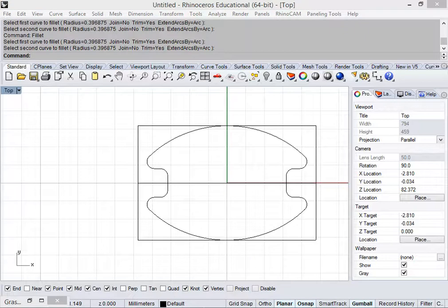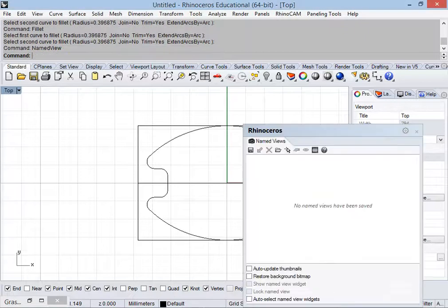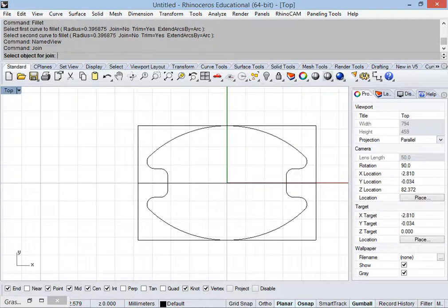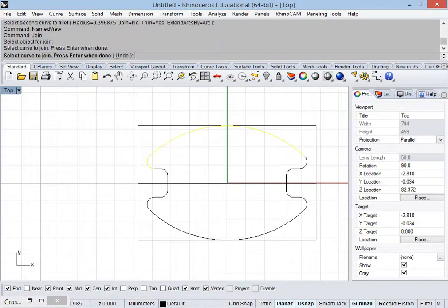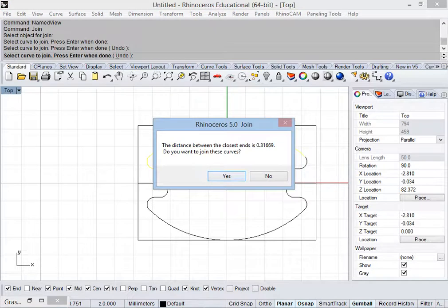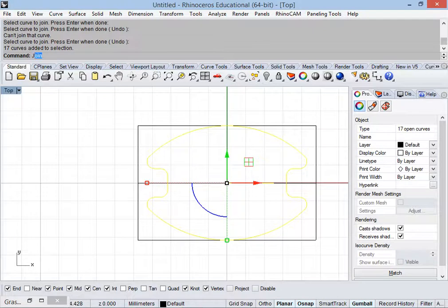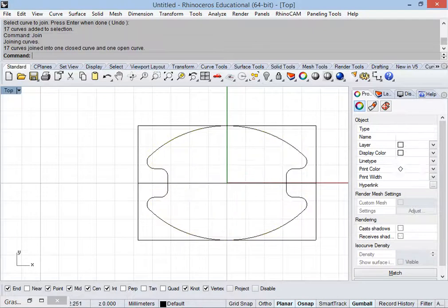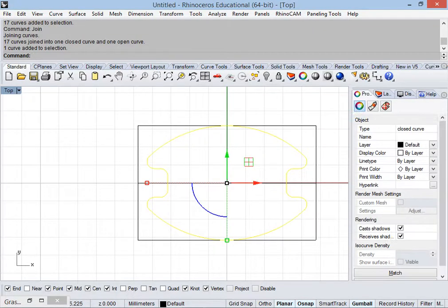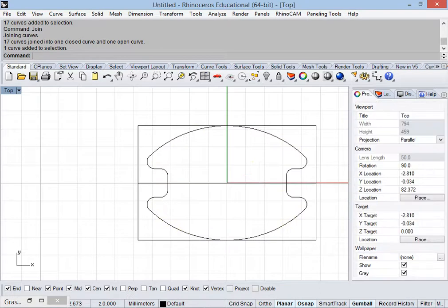We're not going to be fabricating this thing. So then we use the join command. It's easier than doing each individual line. Using a window, type in join. Right? And now we have this geometry joined. Okay. So in this case, we're working with profiles, right? We're always going to be using some type of profile to initiate the 3D geometry.